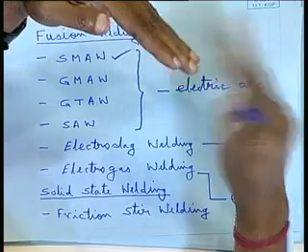By touching and lifting up, what essentially am I doing? By touching, I am completing the circuit. It's a high amperage power source. So, momentarily that touching will generate enormous heat here, right. And by lifting it, what happens? That heat itself, as well as the arc created because of just breaking the circuit by lifting it... you may have observed when you switch off a switch, there is a spark kind of a thing, right. That means when the electrical connectivity gets disconnected, a kind of arc jumps between the two poles, right.